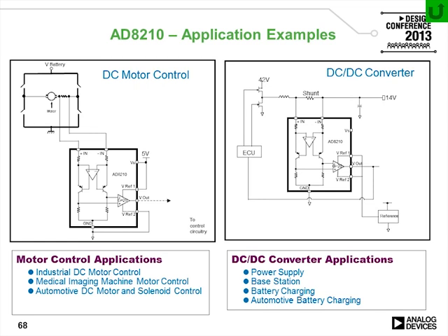In both cases, the shunt is sensing the current going into the load, in this case a motor or a static load, but its common mode is changing constantly. The AD8210 can reject these quick common mode voltage changes, reducing the spikes at the output.